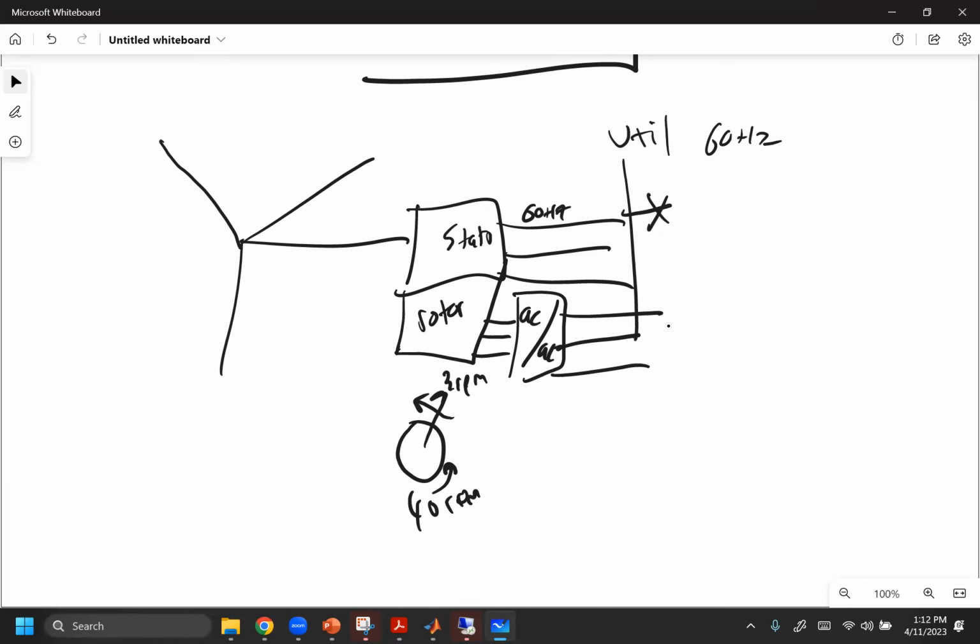It goes to freewheel. The voltage goes in the crapper, right? And we no longer have a current here that can get that magnetic field on the rotor. So the voltage field collapses very quickly, which means my magnetic field goes away, and I just have a hunk of spinning metal. I can't produce any current.